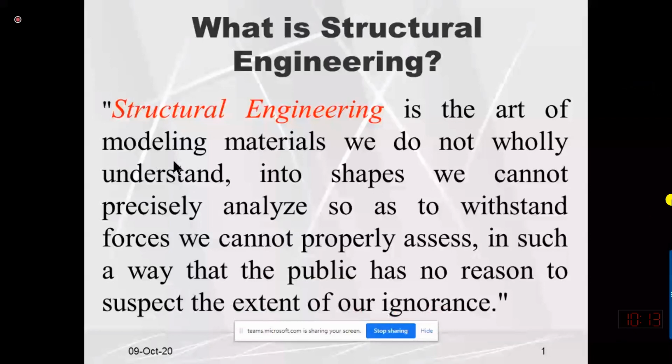So actually, in structural engineering, what we are doing is we want to balance the applied load effect against the material strength. The applied load effect may be shear stresses, tensile stresses, and compressive stresses, and it should be less than the material strength. And then we want to select a structural shape. We want to select the minimum cross section required to withstand all the applied load safely. So we always compute the minimum, and do not go for the higher side, to achieve economy.